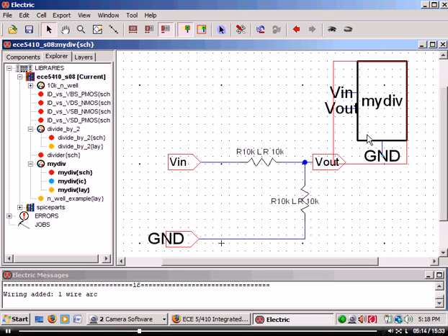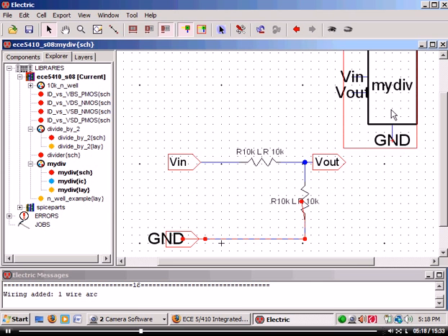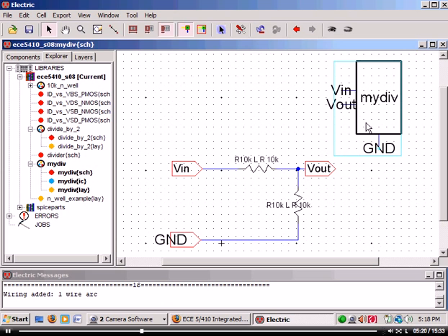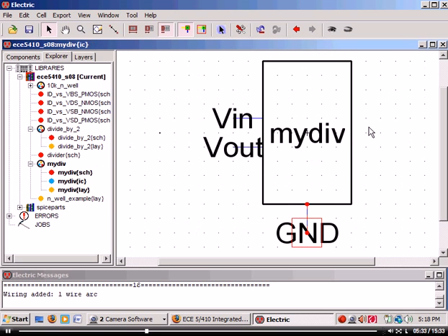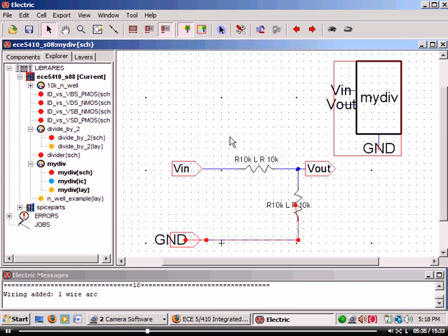This is an instantiated or placed cell. So if I go over and I hit fit, I can now move down into that cell by pressing what? Control D, just like I moved down in my NWL layout. So I can press Control D and go down and edit that, or I can press Control U. Now notice, it just puts it there so you can see what the symbol for the cell looks like. You can see what the schematic looks like, and then you can see what the symbol is, just so it's